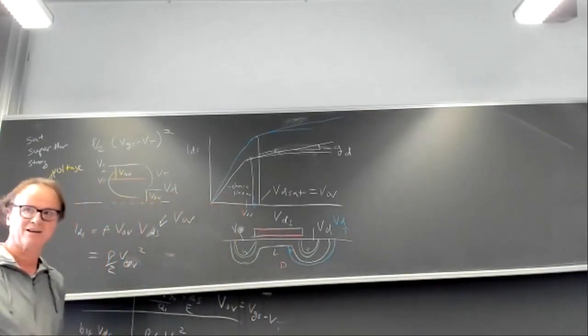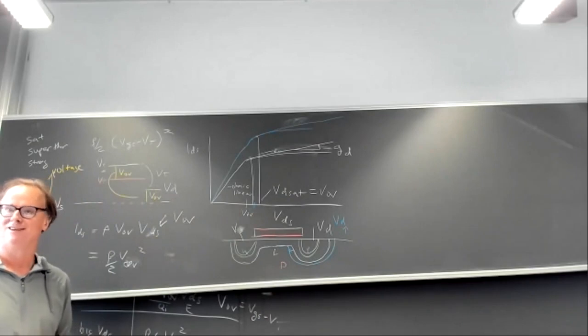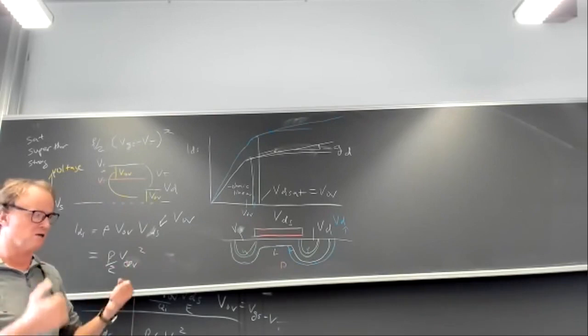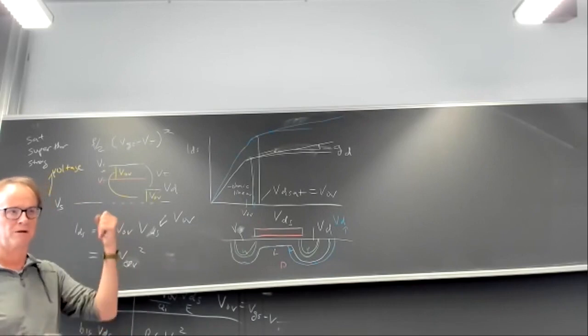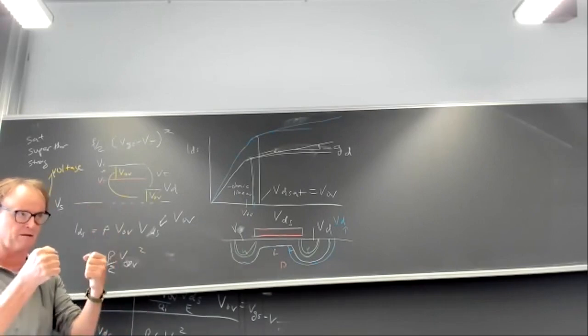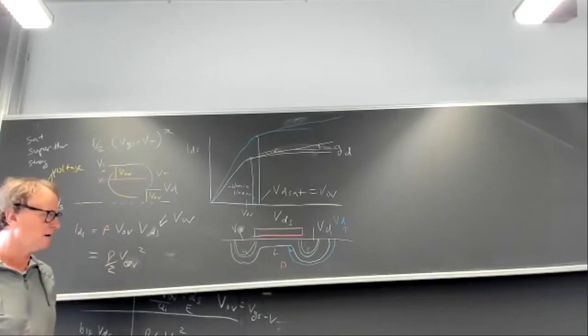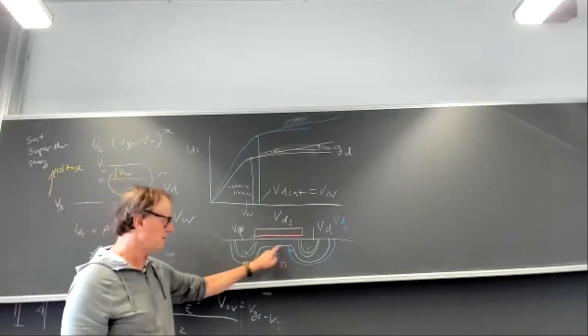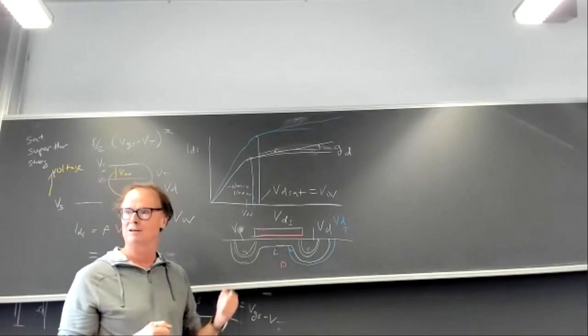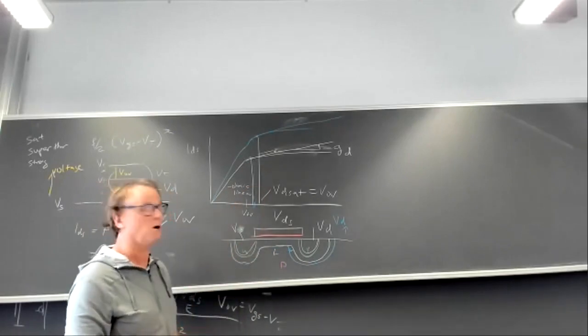And do you remember this factor of 1 over L? The shorter the transistor, the bigger the electric field. Or in subthreshold, as you'll see next week, the shorter the transistor, the bigger the concentration gradient, right? Because you have the same concentration ratio, but shorter length. It's going to make a higher gradient. Either effect, increasing the electric field or increasing the concentration gradient, both increase the current. And so that's why there's a slope on this curve.